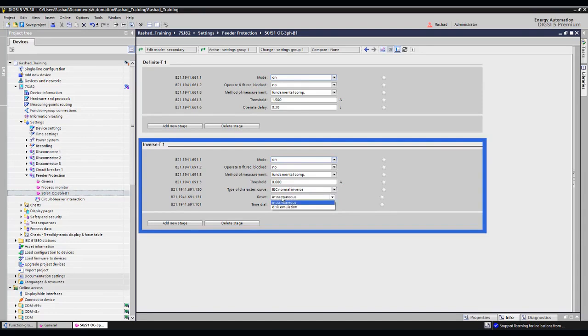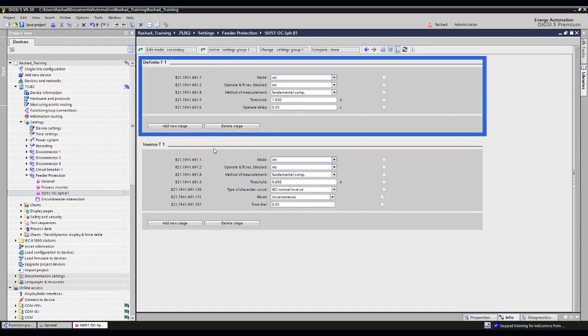The idea of the disk is that it takes time in the reset, like the electromechanical relay. It has picked up, so the disk started to rotate. And on the way, the disk also returns with its momentum. Therefore, if a pickup occurs again in the middle of the journey, it will continue from where it stopped, not from the start, and it will not start counting a new time. This is what it wants to tell you. In numerical relays, we always use instantaneous reset, meaning once the pickup is gone, and if another pickup occurs, I will start over from the beginning. And this time, for example, is set to 0.5. And like this, I have set the function.